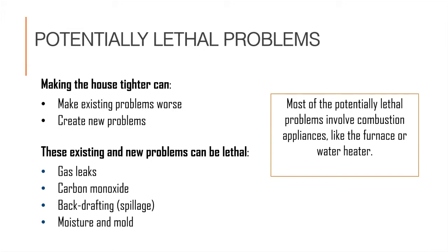In addition to the buildup of gas leaks or carbon monoxide, other potentially lethal conditions can arise from depressurization and backdrafting of natural draft gas appliances like water heaters or older furnaces, which can also lead to spilling combustion byproducts into the living space. Air sealing a home also traps in moisture that probably used to get flushed out through previous amounts of shell leakage, and the newer, higher humidity levels can lead to potentially harmful mold as well.